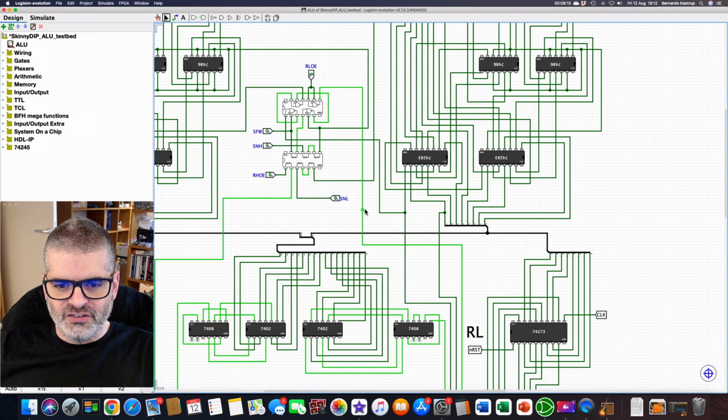There are no branches. The trace is not branching out to go elsewhere. When traces branch out a lot to go to multiple different places, you get a lot of impedance mismatches on every branch. You get lots of reflections that pile on one another because each branch has a different length, so you get different reflections. You get more EMI because the branches begin acting like little antennas, fractal antennas that go all over the place in the PCB. So those are the signals you have to worry about to take countermeasures, so to say.